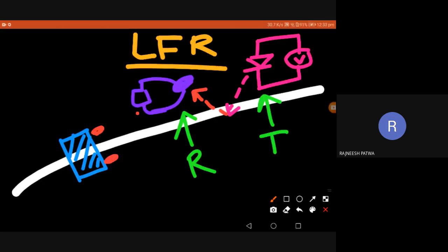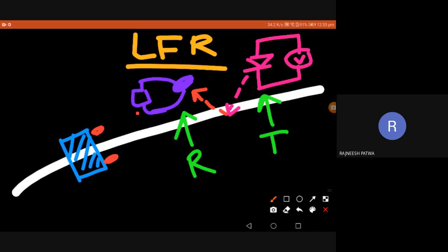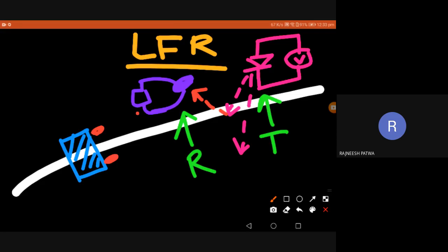So what is the transmitter doing? It's always sending radiation whenever it is on. But we should remember, when it comes across a white line or light surface, it reflects the majority of the radiation, and the receiving sensor, which is sensitive to IR, catches it. But when the IR radiation falls on a dark surface, what happens? There is very little reflection, and maximum absorption.